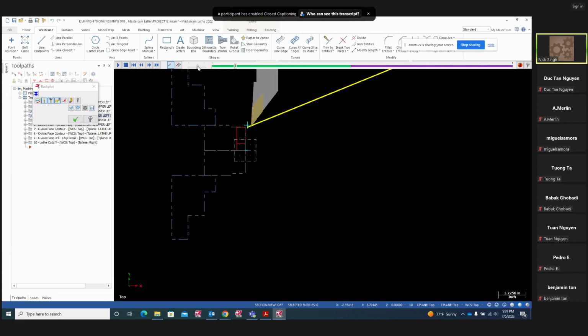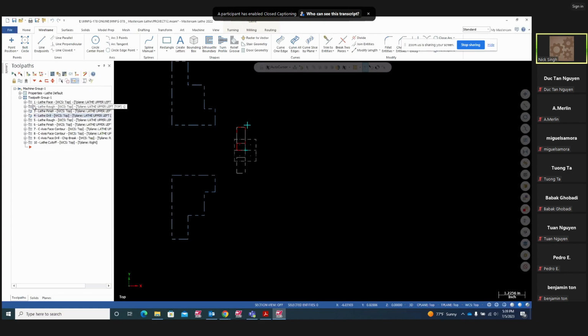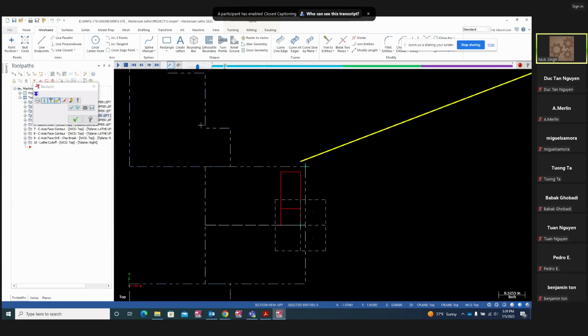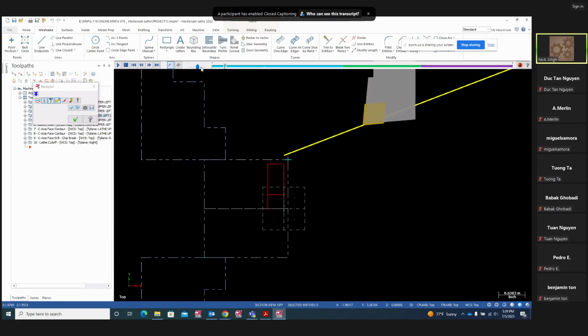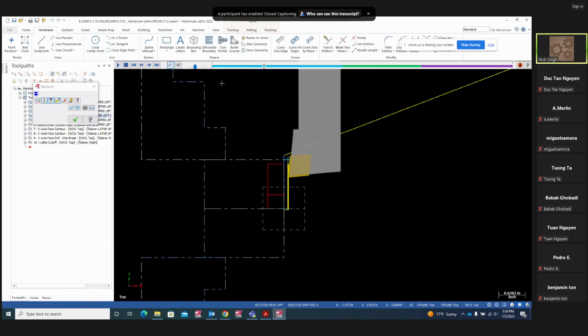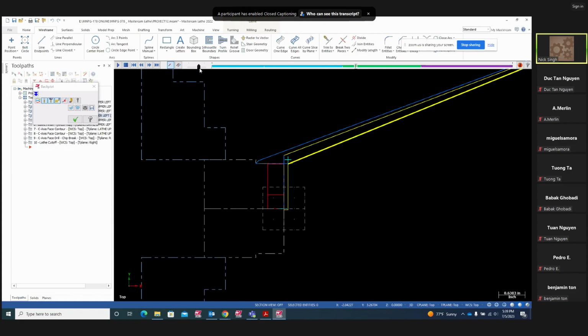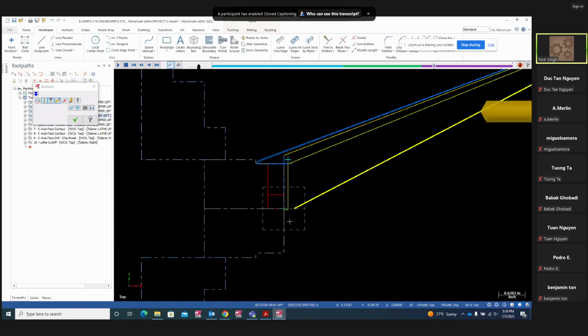Here, we are just turning it. I skipped facing, did I? Yes, I skipped facing. So here's a face and OD rough, and OD finish. And then I'm going to get a drill. I'm going to drill right on the center. There we go. That's my drill.